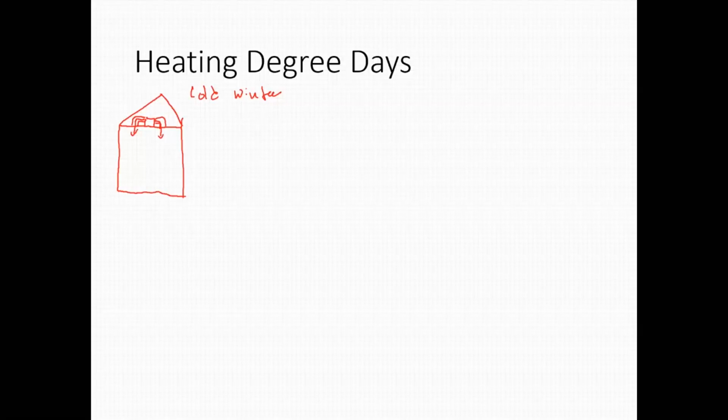If you're trying to cool your house and your thermal envelope stops at your ceiling, and your roof deck is 200 degrees and it's 180 degrees in your attic, and your HVAC system is up there, and you're trying to pump cold air into your house, but you've got cold ducts in a vented attic with warm humid air, your ducts are going to be sweating, and you're going to have heat gain into your ductwork from your hot attic. So it's a good practice to put your HVAC systems inside of your thermal envelope, just as an aside.